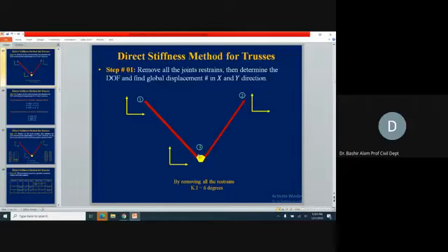If you see here, with the horizontal, it is making an angle of 45. So this will become 180 minus 45, whatever is coming, 135, that is becoming his counterclockwise angle. So if you take this joint 3 as your starting point, this 135 degrees becomes your angle then.